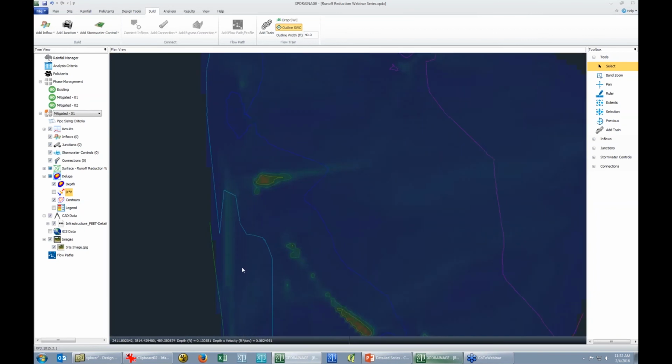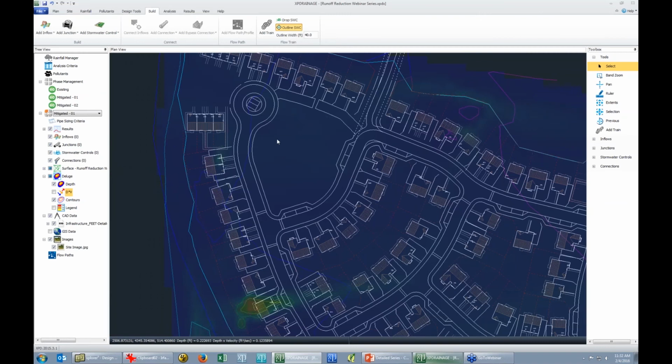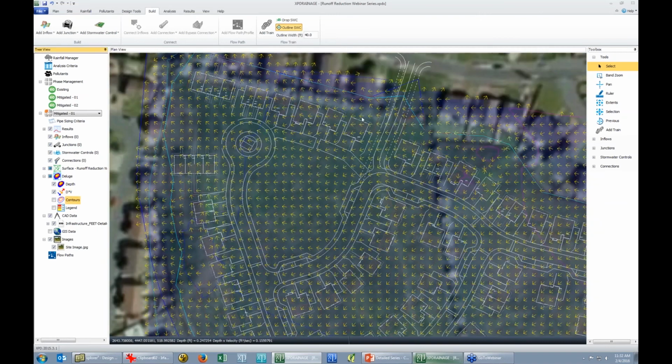Okay, well let's look at delineating those inflows. So the first thing we might do, again, looking at my deluge. All right, well this area is going to be a little park zone. This area really predominantly runs down to this corner here. So perhaps our first facility, our first treatment, will be right down here in this corner.